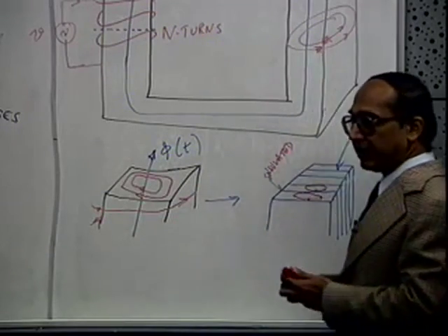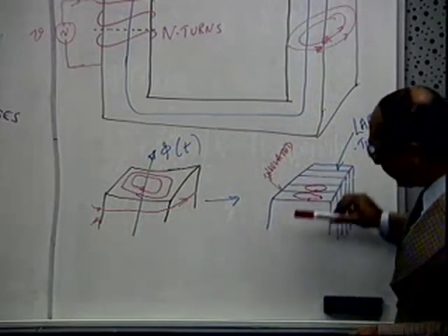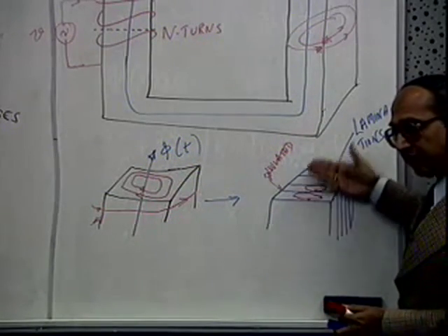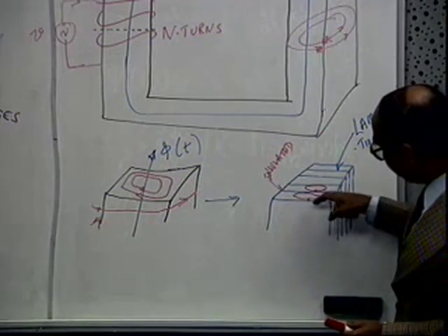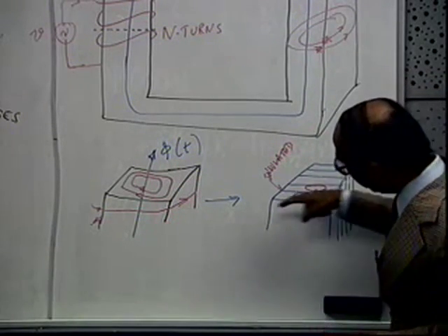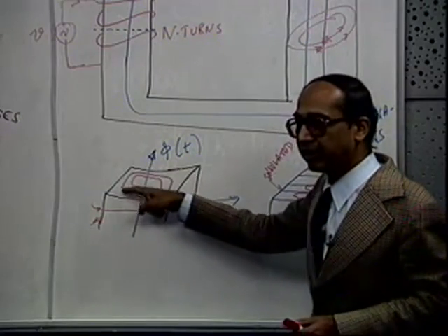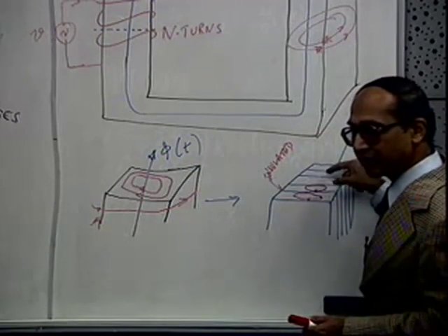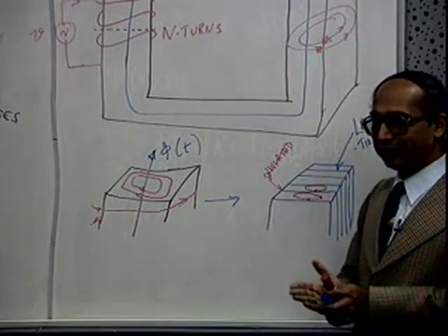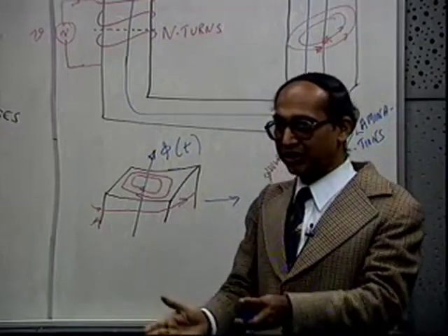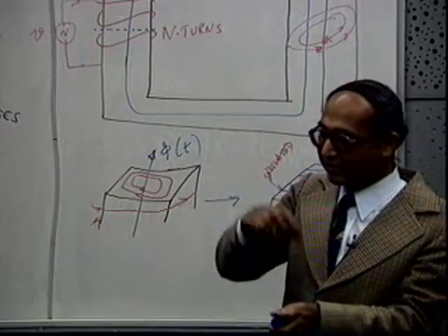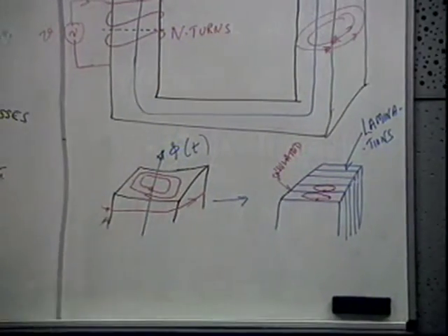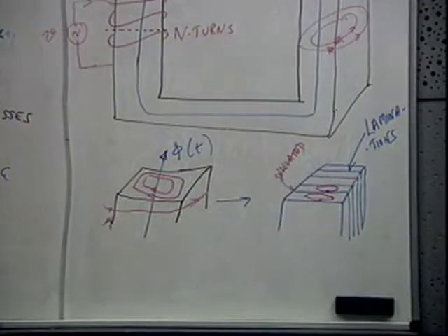Here, the flux is also reduced in each of the sheets in a way. And the flux density, then, this is one resistance path compared to several resistances like this. If you have a thick sheet and make it into smaller sheets, obviously the currents in each one of them will be smaller. Pardon? The resistance is also decreasing? The flux is also decreasing?